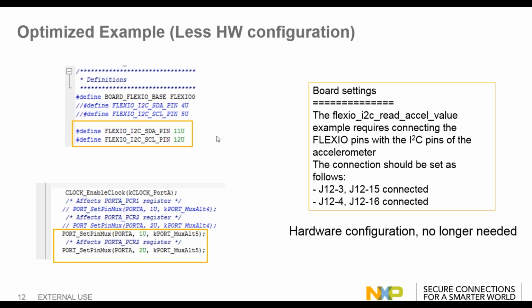And we also have to change the pin multiplexing to set PTA1 and PTA2 to utilize the FlexIO multiplexing option on the device.